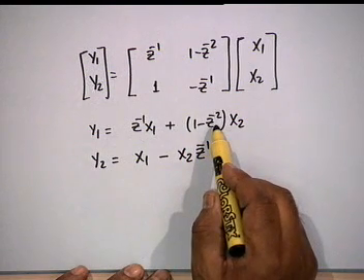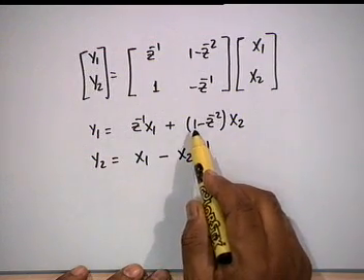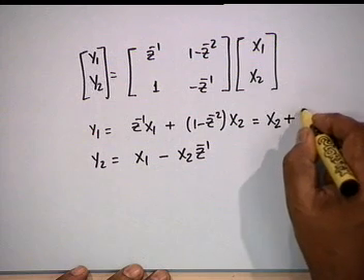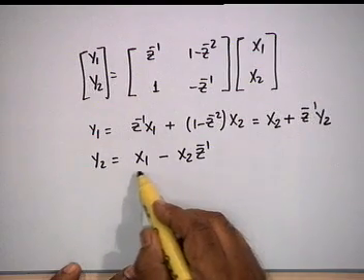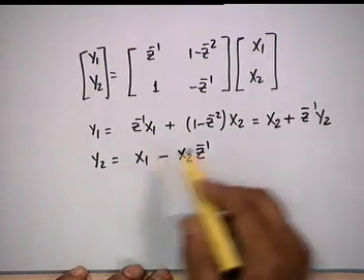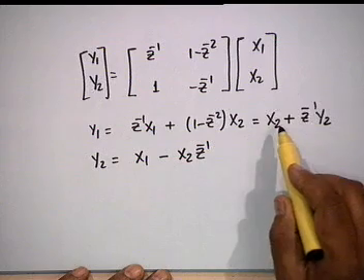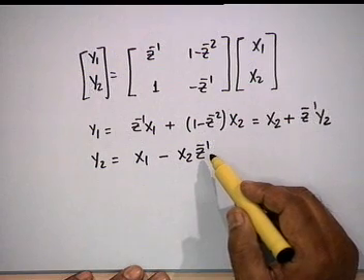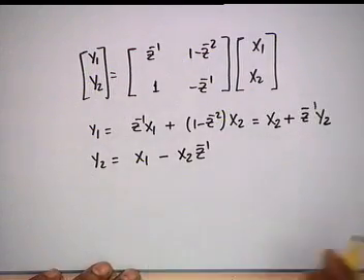Both of these terms are present in the first one, isn't that right? In addition, in the first one we have an x2. So, I can write this as x2 plus z inverse y2. I can realize y2 by 1 delay, then I require to construct y1 from x2 and z inverse y2. If these 2 delays can be shared, then we have done our job. Okay? So, if I want to construct this,